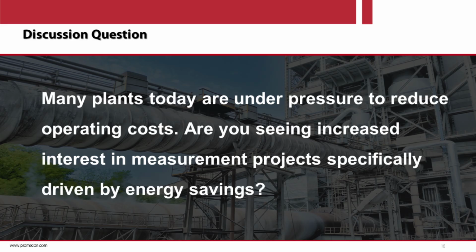That's two examples. The third one would be measuring the airflow at the cooler vent, which is necessary to do a good calculation of the cooler mass and heat balance. And as we know, the cooler is where all the combustion air for the pyroprocessing is generated. So that will enable better control of the cooler fans, whose flow is difficult to measure, as well as the important point, which is the kiln hood draft.